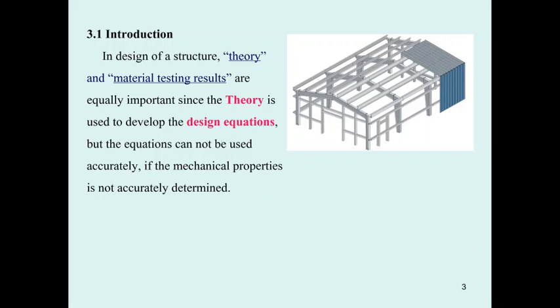However, when you are the site engineer and the producer sends the steel to you, you also have the duty to check whether that steel is acceptable or not. Usually, for every 50 tons of steel, you may cut 3 bars of 2 meters each, and then you send those specimens to the lab.